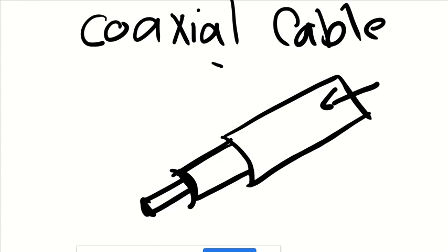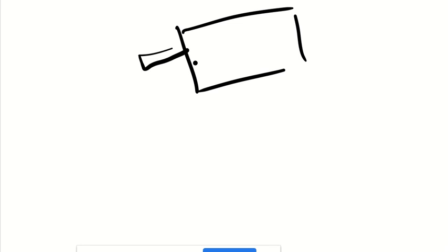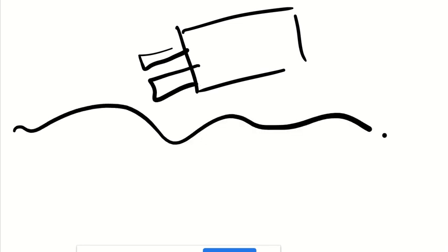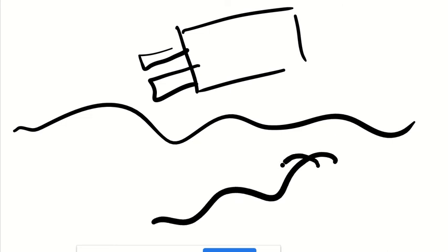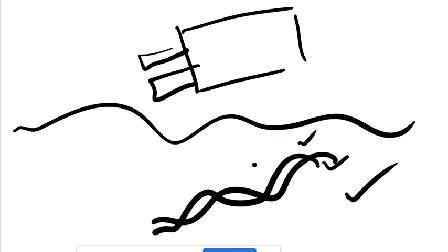Another example of transmission line can be parallel wire lines, but you don't see them around anymore. What you see is lots of twisted pairs, twisted pair cables, where two insulated copper wires are twisted together. They're used in local area networks a lot. So twisted pairs and coaxial cable are all transmission lines, okay?